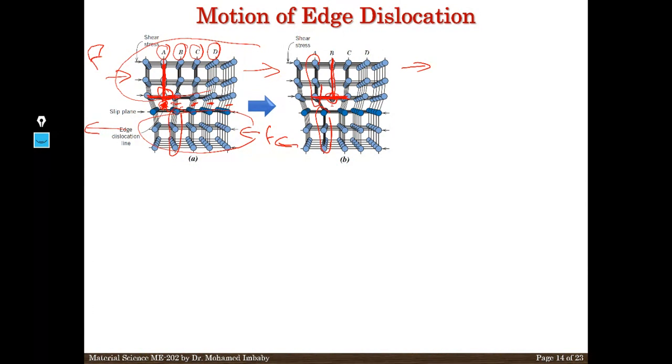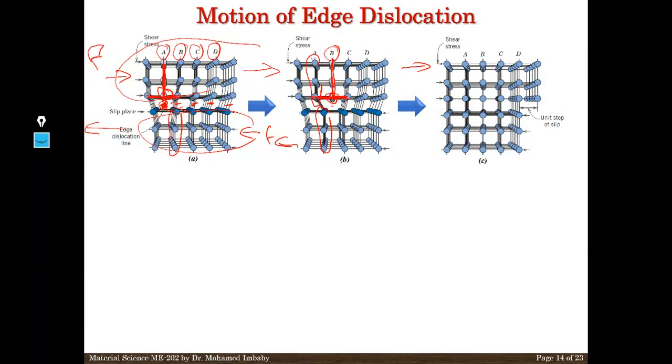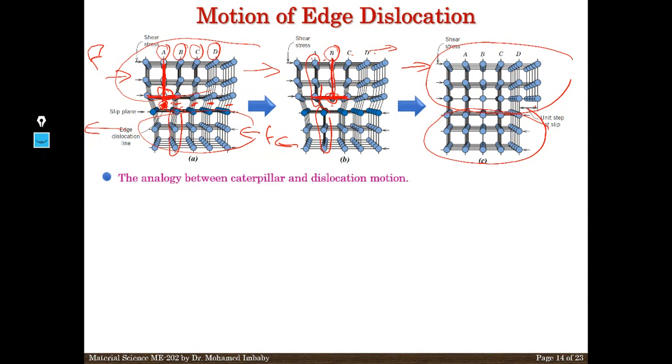So in the second step, A was where the dislocation was. Now there is no dislocation at A. The dislocation moved to B. When you apply the force again, the movement goes from B to C and finally to D. So the material will be in motion here. You get the point, guys. Look at here. I think it's very clear from here.